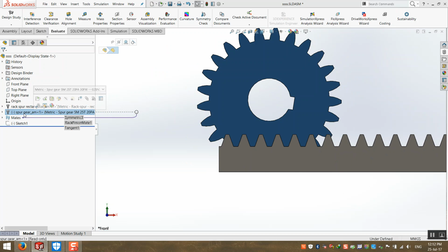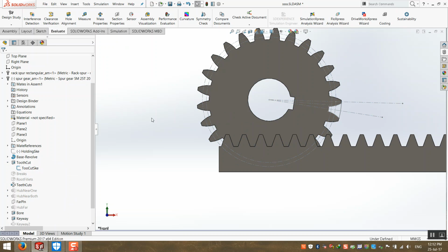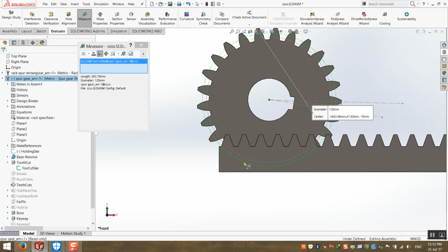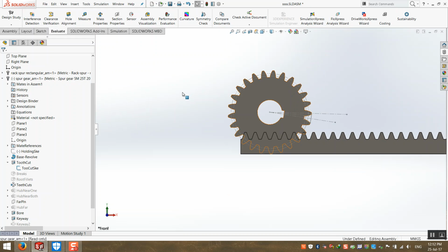There is an option, but it is too complicated for you to learn now, when you are going through an actual mechanical implementation. You will reduce the diameter to a smaller one but keep the same number of teeth, so the rotation will be the same. This is how you can reduce the size.